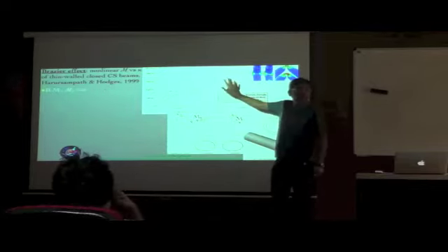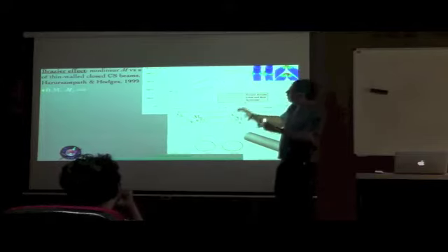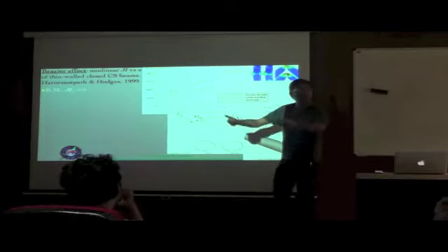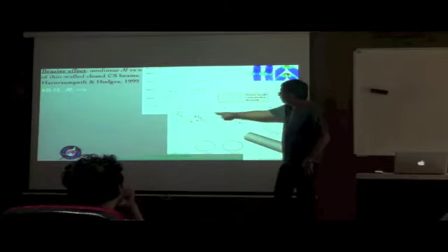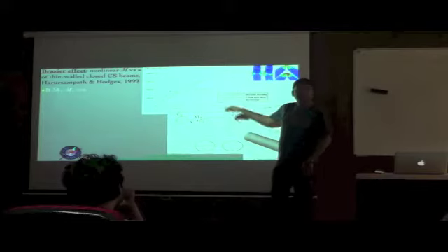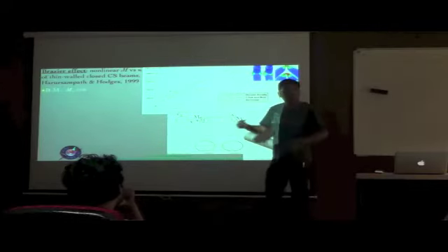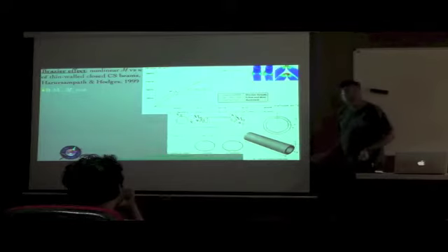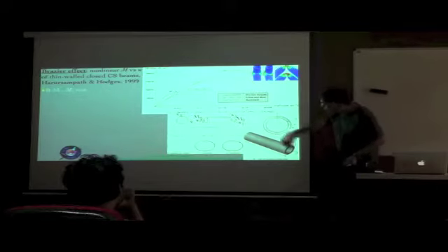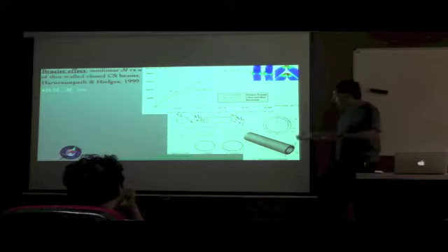This is different from local buckling. This is a much more macro scale instability that we are talking about. So these are different aspects of failure, and depending upon the actual material that you have, in this case graphite epoxy, and the actual layup that you have, what the thickness is and what the ratio of that thickness to the radius is, and again what the ratio of the radius to the length is, and the moment itself, of course.